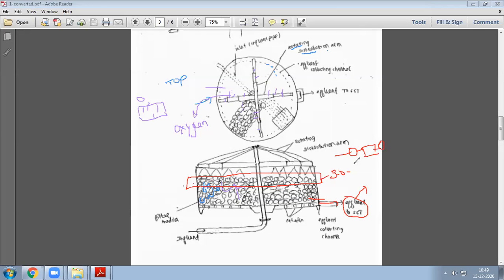This is how your treatment will usually look. Here a secondary clarifier sedimentation tank will be there, so it will pass to here. Further settling will happen. If anything is remaining, it will settle to the bottom. Or if you want, you can take it directly from an effluent collecting tank. Here we can collect it, or you can pass it to the next chamber.